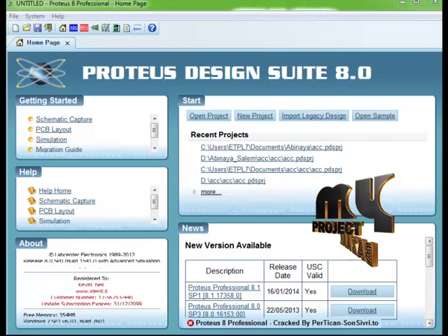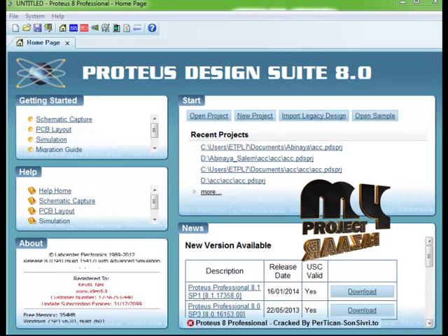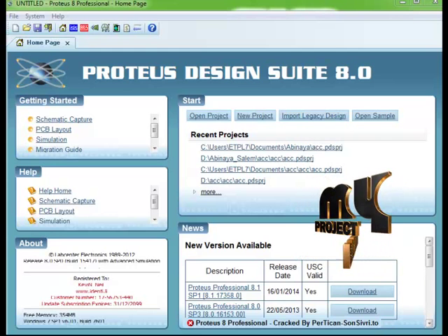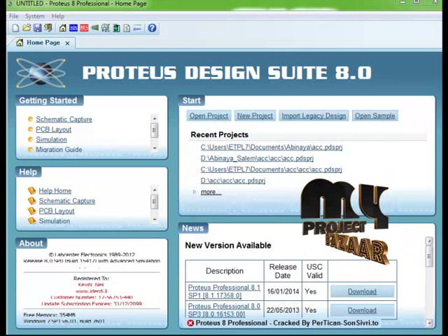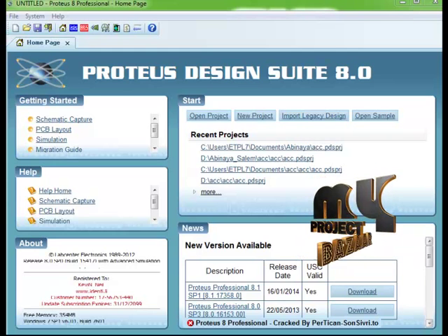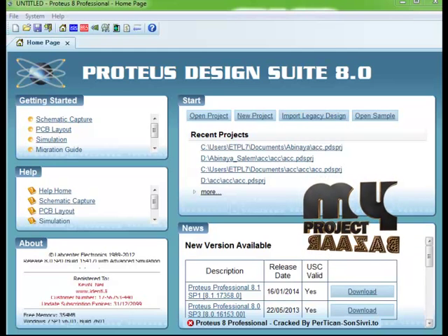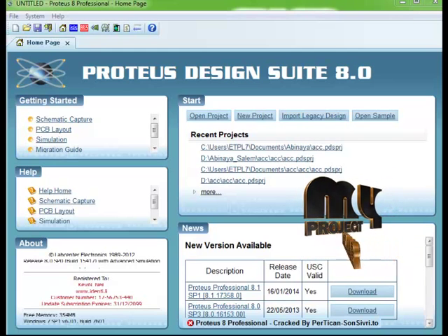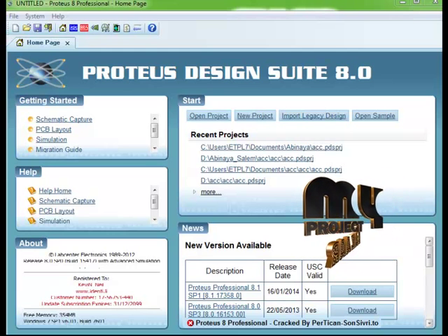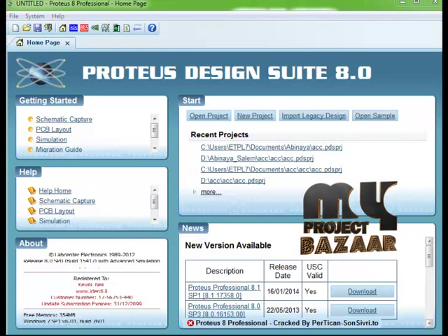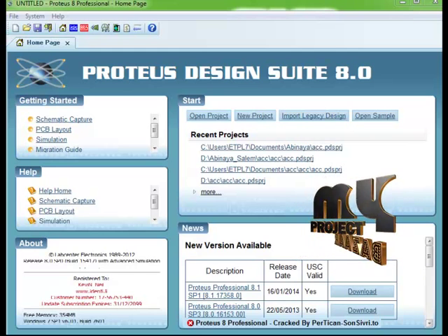The drivers provide RS-232 voltage level outputs from a single plus 5 volt supply via on-chip charge pumps and external capacitors. This makes it useful for implementing RS-232 in devices that otherwise do not need any voltages outside the 0 volt to plus 5 volt range, as the power supply design does not need to be made more complicated just for driving the RS-232 in this case.